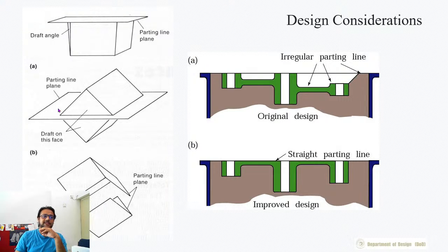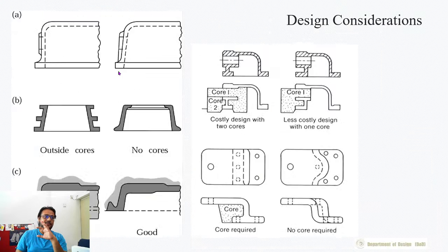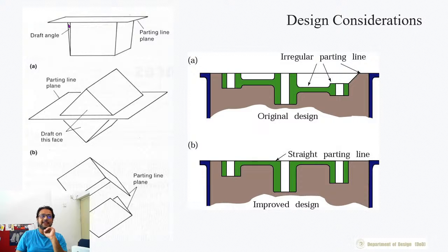You can orient it in another way, and you have at least 2 or 4 sides which are 90-degree, but one side you need to machine to make it 90-degree. In this way, if you want to cast a cube, you will always have to give some draft. So it's possible to orient the parts that you design in a manner that will give you the closest to what you want. That is just an interesting exercise for a class.